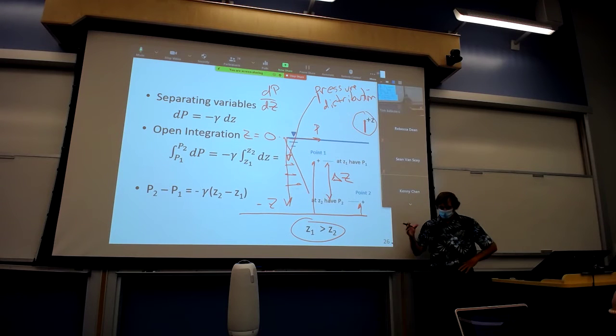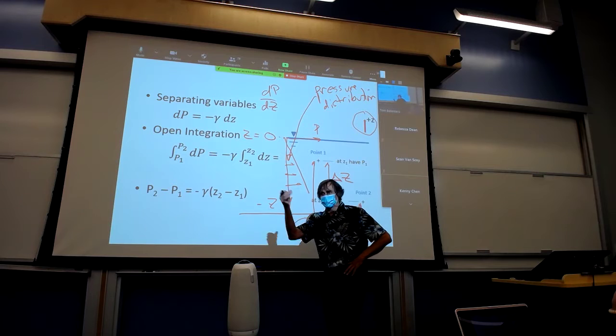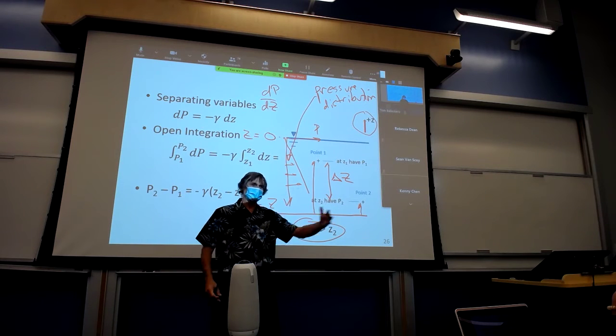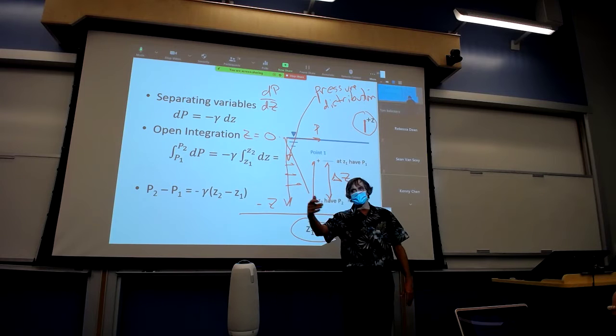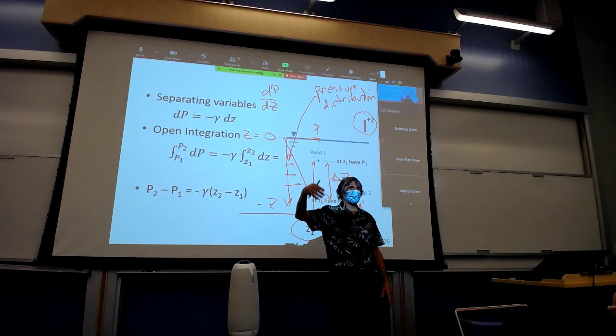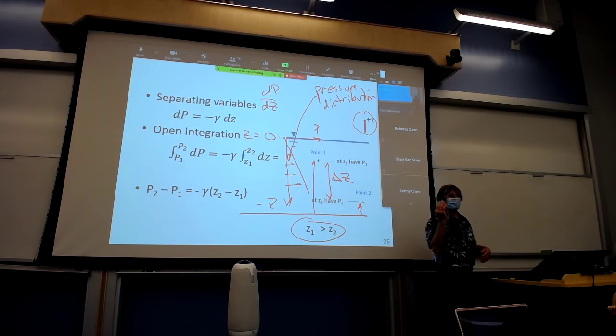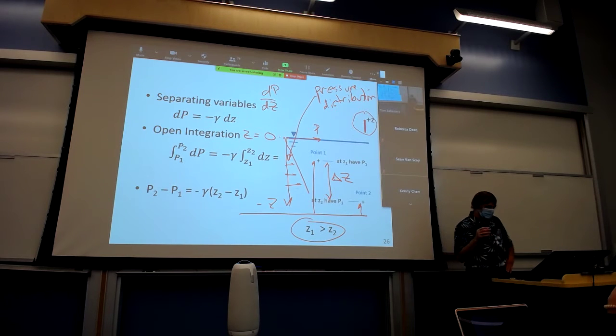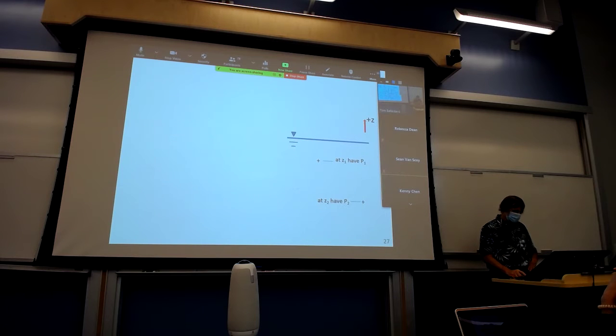And if you recall, when we started out this talk, we want to know that. One of the examples I showed you was the dam. On one side of the dam, you don't have water. On the other side of the dam, you do have water. We will take that pressure distribution and integrate it over the upstream side of the dam to get a force. Or any other fluid-solid surface interface you can think of. That's what we need to do to convert the pressure distribution into forces.